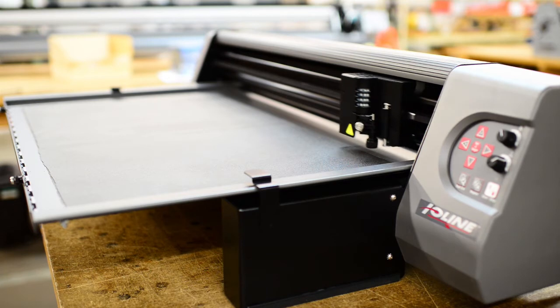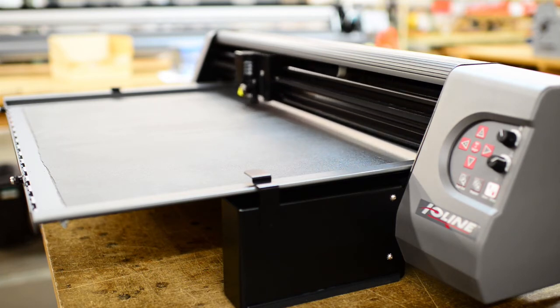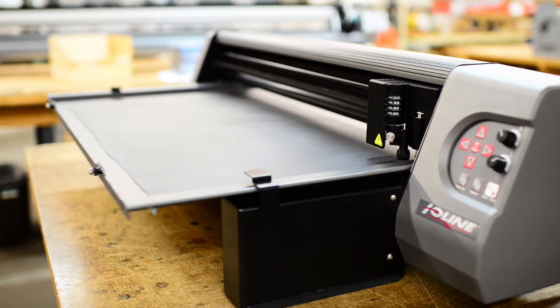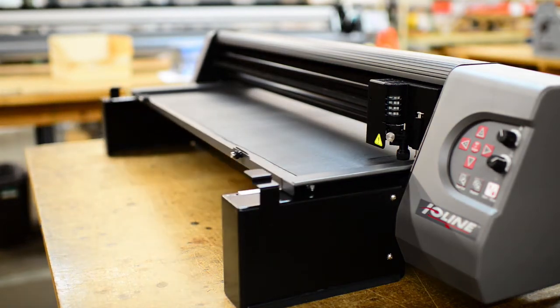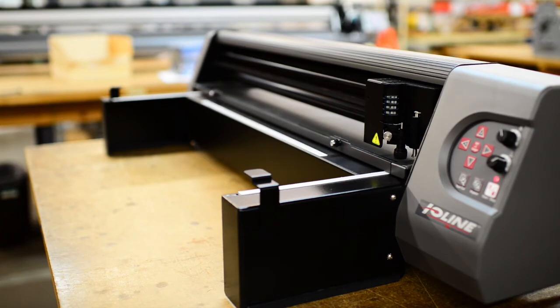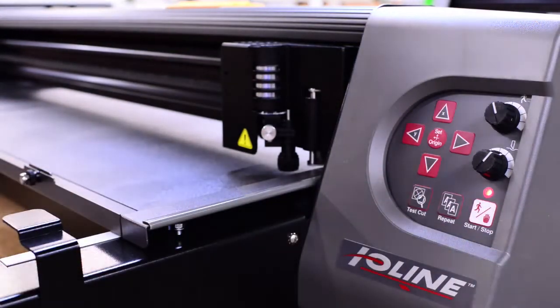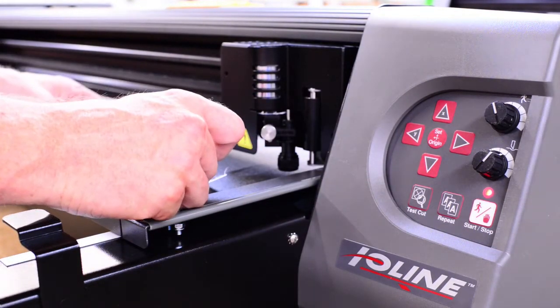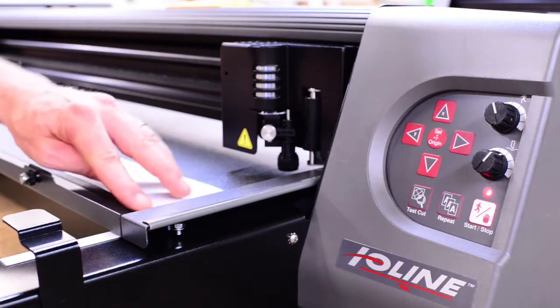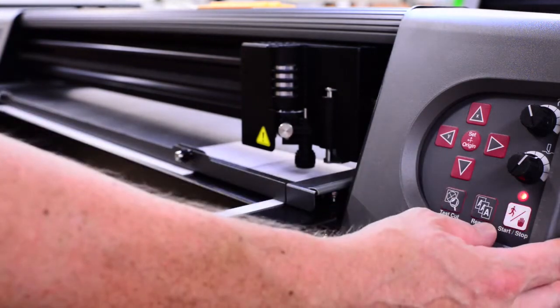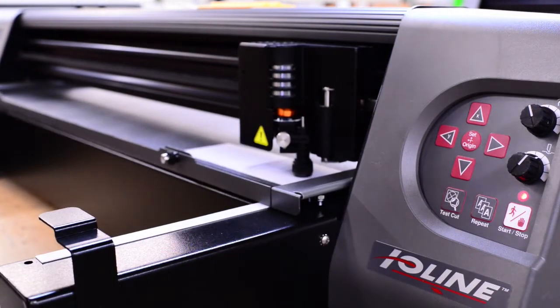And what we're going to do first is a test cut on another piece of twill that's sitting on top of this first piece that I put down. And by doing this, we can tell if it's cutting through one layer at a time or if it's going to cut really deep through both. So once the machine is initialized, just pull the tray forward a little bit. And I've got a junk piece of twill here that I'm sticking to the bottom layer. And then move it over to a place to make a nice test cut, and hit the test cut button. And it'll do a little square with a circle and pie pieces, and it should cut out nicely.